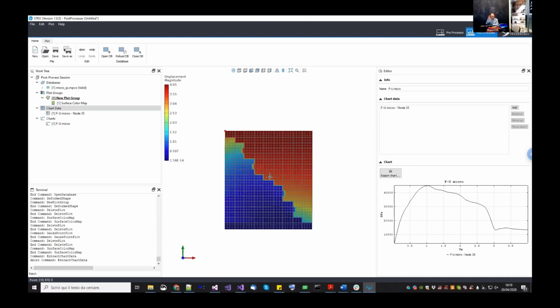But sometimes, or most of the times, it happens that you don't have all those experimental data. You just have few data on the entire masonry assembly, not only on the constituents. In that case, probably it's better to do homogeneous modeling. But there is a problem for homogeneous modeling. Most of the software either do not have a very good material model for concrete and masonry, or if they have it, it will be very hard to reach convergence with those kind of models.